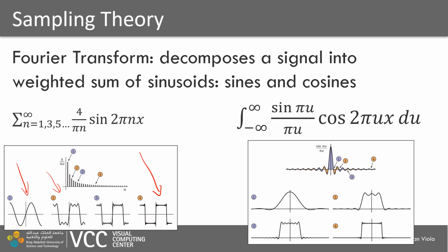So we can see it on our frequency spectrum. Here would be the two frequencies and their corresponding intensities or amplitudes. And we can see that even further refining the values of our additional sine waves and additional frequencies, we can get closer and closer to representing a high frequency signal.